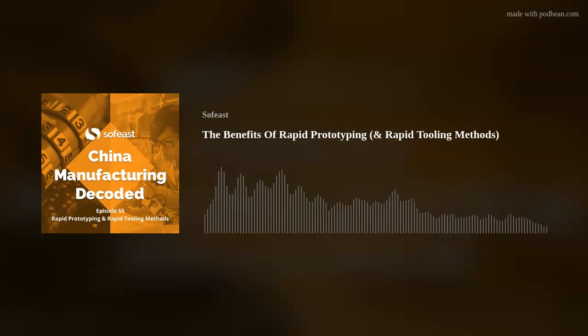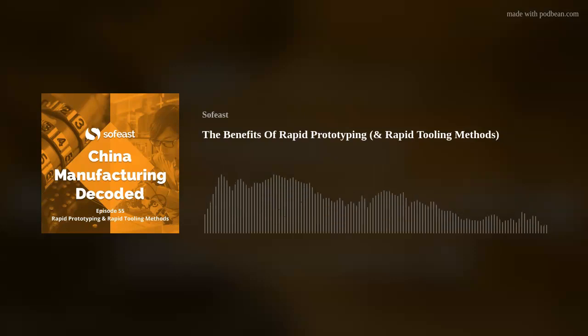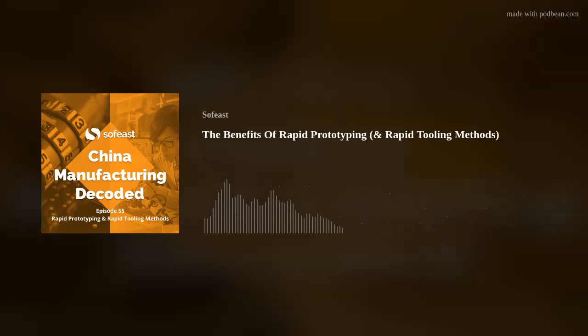So you make the silicone mold, and then after that you use a thermoplastic polymer that has a much lower melting point, obviously, and it gets into the mold. You close the mold, let the thing solidify and cool down, and you take it out. Again, you cannot make parts with high accuracy here.